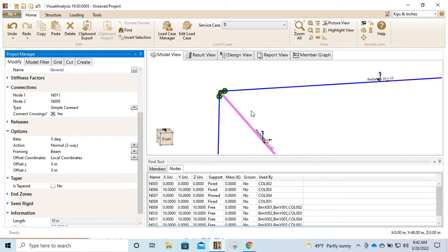So you're just going to essentially, Adam has an example of somebody that called in and says, I'm getting no displacements in my model. And they fixed every node in their entire model. Okay?